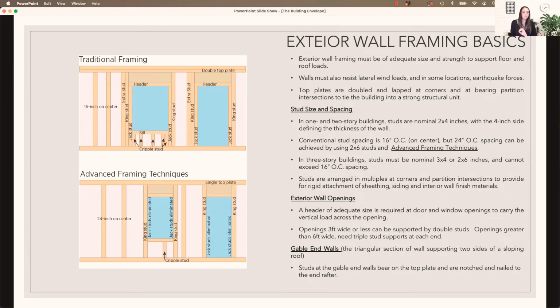If you measure and do a test and put a nail into the wall and you don't feel like you're hitting something dense, then it might be 24 inches on center. There also are stud finders available that help you locate studs. But we're also going to talk about another way to approach providing that anchoring without having to locate a stud. So again, 24-inch on center, that's the advanced framing technique. I do have a video next that's going to show you some of the best practices when using advanced framing and how it can help with climate control and things like that.